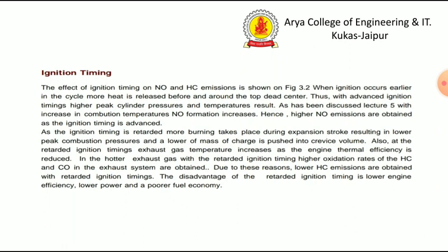The exhaust gas is hotter with retarded ignition timing, and a higher oxidation rate of HC and CO in the exhaust system is obtained. Due to this, lower HC emissions are obtained with retarded ignition timing. The disadvantage of retarded ignition timing is lower engine efficiency, lower power, and poor fuel economy.